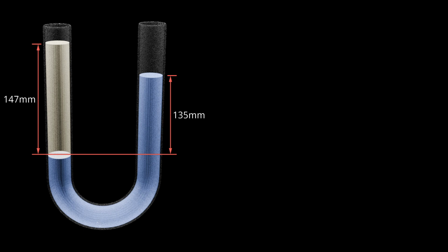Because if the fluid were moving, the pressure at the same height wouldn't necessarily be equal. That falls under a different topic in fluid dynamics, which is governed by principles like Bernoulli's equation. But in our case, since the fluid is at rest, we can confidently say this. The pressure exerted by the column of oil above the interface is equal to the pressure exerted by the column of water above it. And that's the key to solving this problem.